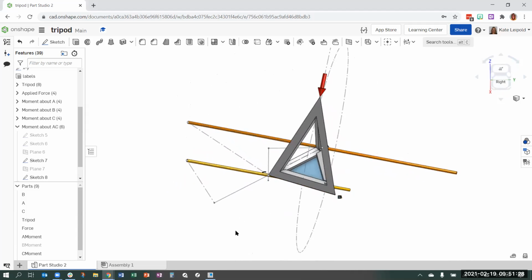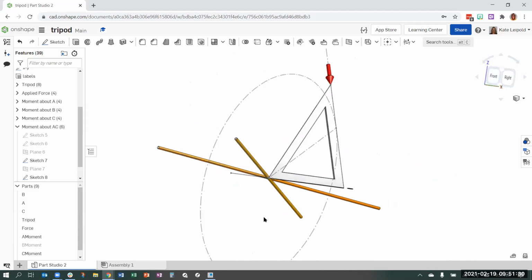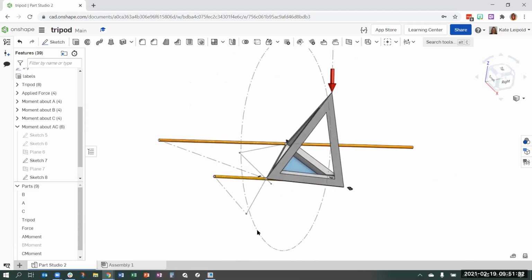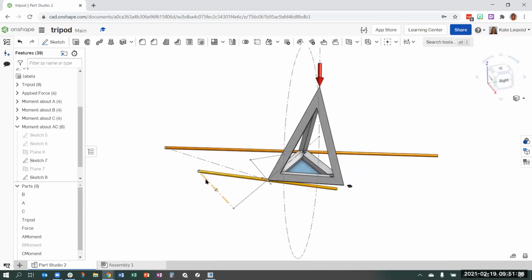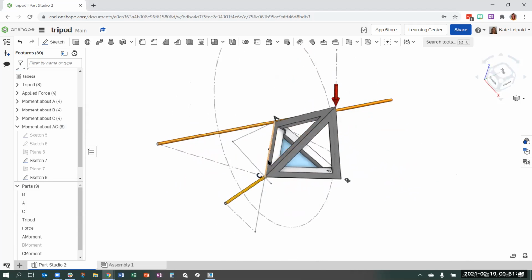And then finally, how we can use those planes. They're not horizontal and vertical necessarily, but we can include planes to show projections of moments onto edges and how this force at the top causes a rotation around AC. We can calculate that out with the moment about C or with the moment about A, and we'll still get the same tendency to rotate around that axis.